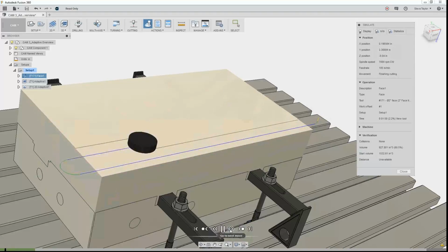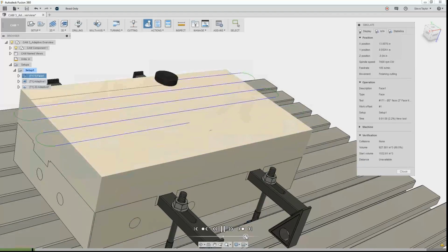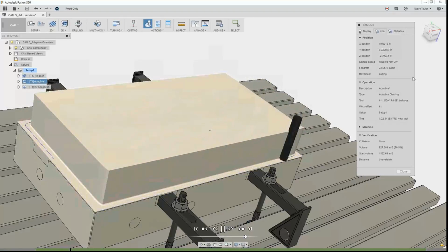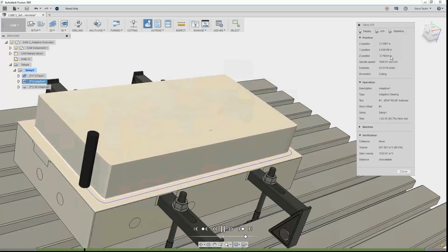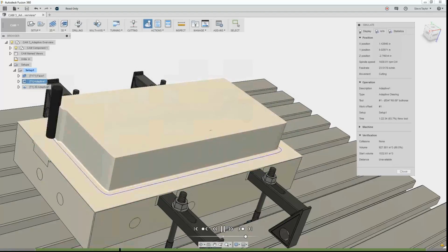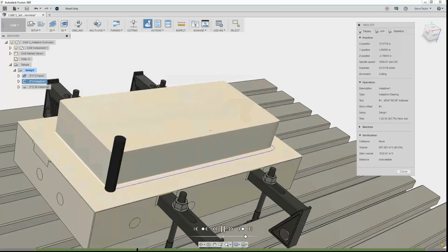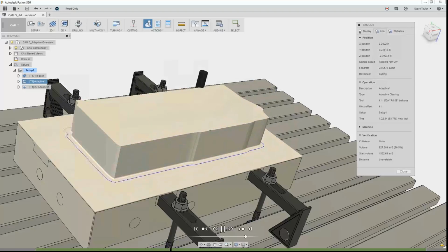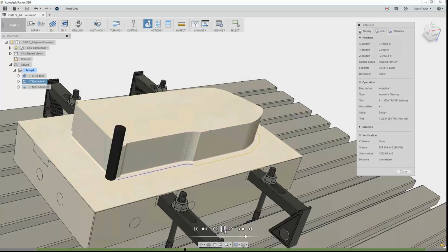I've got some controls. I can move to the next move. I can speed, so I can increase the speed of the cutter as it moves along. You can see how the information, the position is changing in this information up here, what setup we're on. So it's faced the top, then it's doing our 3D adaptive clearing. You can see the depth of the tool in the material. We can pause the operation if we want to do. You can see we set a maximum of 80% of the flute length, which, you know, we're not near there.